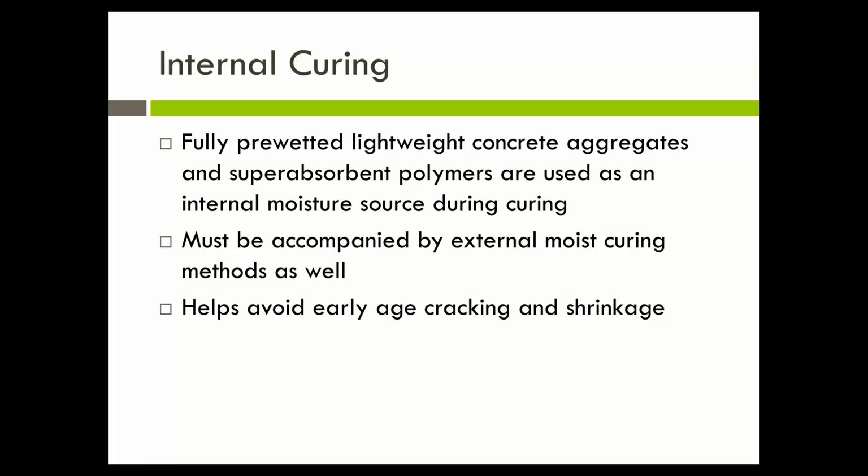There are a lot of people that have been working on internal curing. Internal curing uses an absorbent aggregate that holds water within itself, or a polymer, the kind of polymers that you would find in baby diapers, or super absorbent polymers that swell up when water is exposed to them. If you put those in concrete, either the super absorbent polymer or the lightweight aggregate, that's aggregate with a lot of void in it, then that carries in water, and as the concrete around it dries, it will give up that water and give it back to satisfy the pressures that are generated by the evaporation of water, and so you can extend curing, and it's really quite effective.